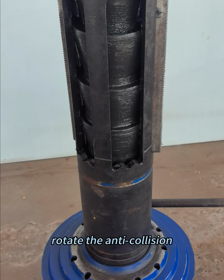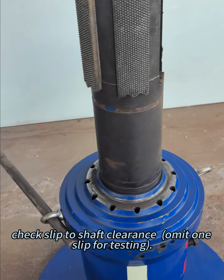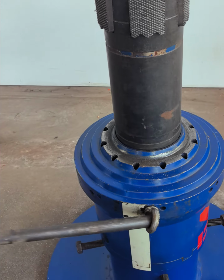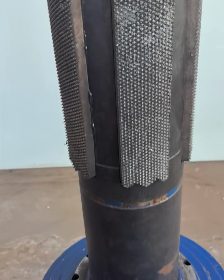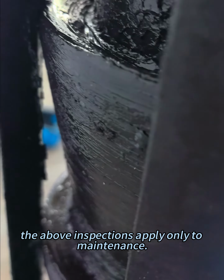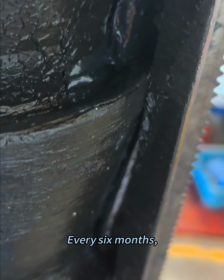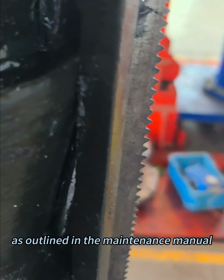Rotate the anti-collision plate counterclockwise for release. Check slip-to-shaft clearance, using one slip for testing. The above inspections apply only to routine maintenance during daily use, under normal operation. Every 6 months, perform a disassembly inspection as outlined in the maintenance manual.